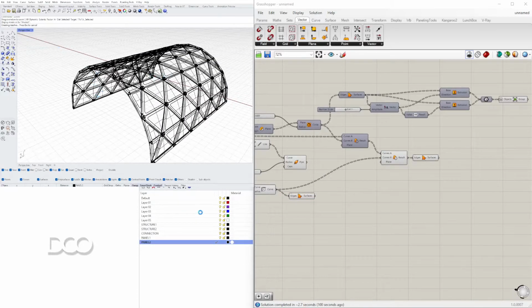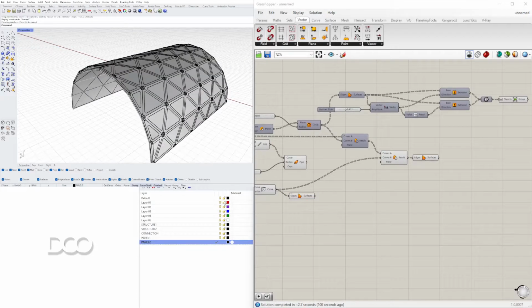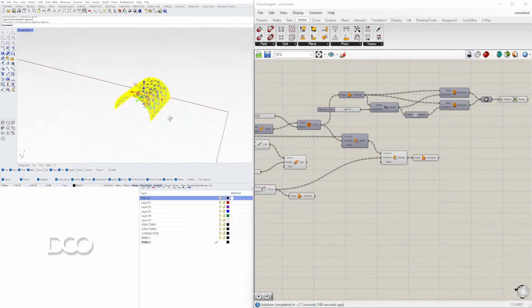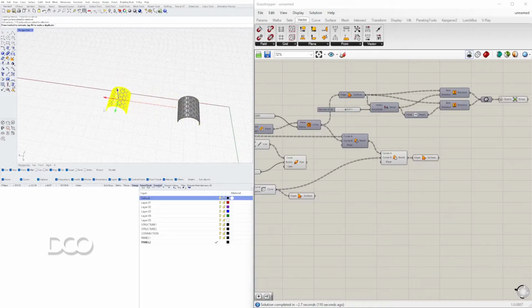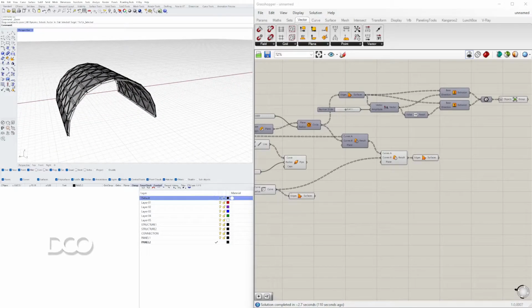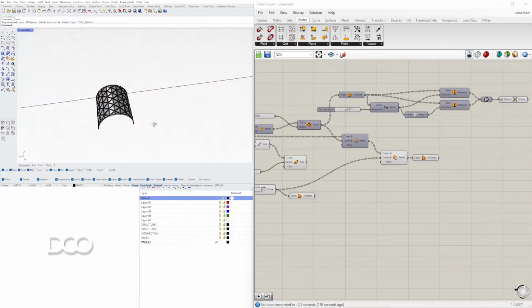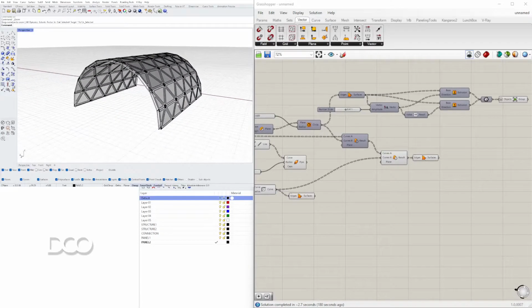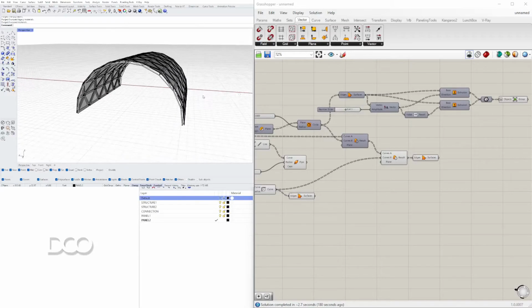We'll go here to shaded mode, and I'll lock the default layer, which is the layer where I created that surface. This way I can take all of this and move it to the side. I'll type in zoom selected. Cool, so now that we baked all of that stuff and we have everything else hidden, I'll select this, go to ZS for zoom selected, and I'll type in purge so I can get rid of all of the layers and stuff that I'm not using.